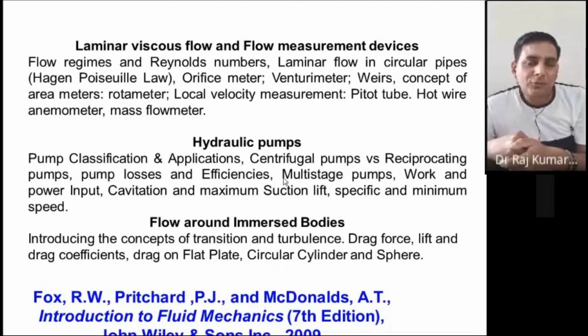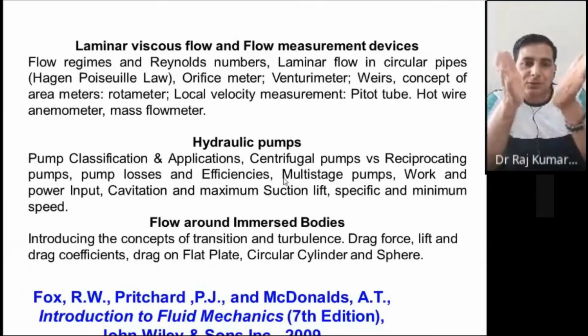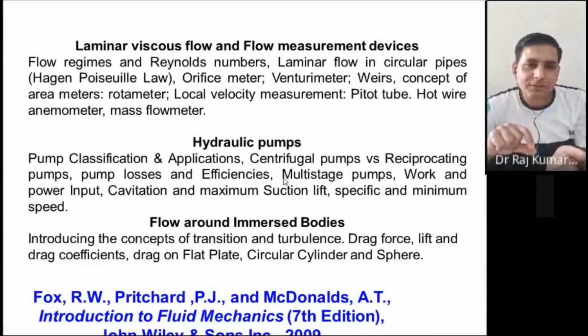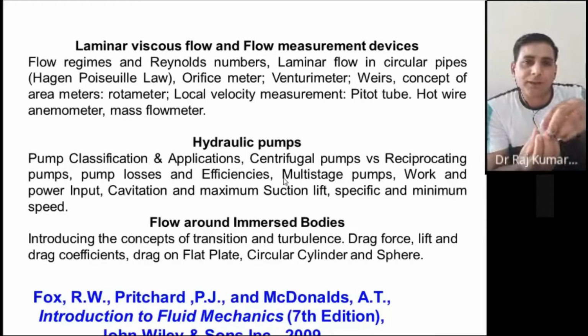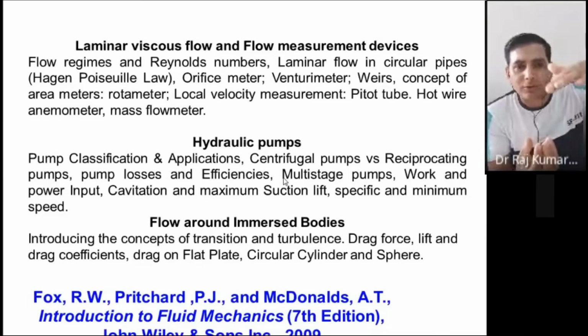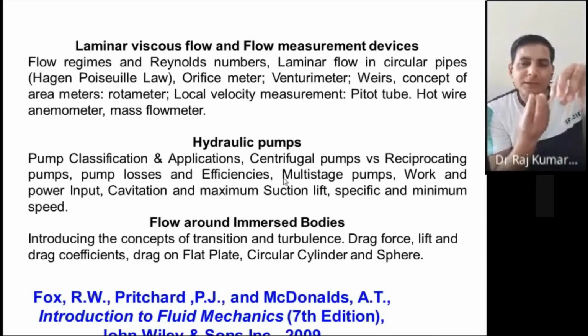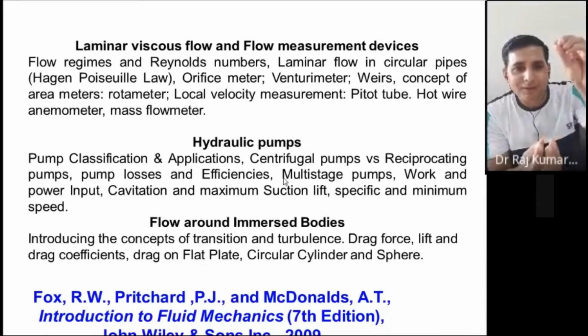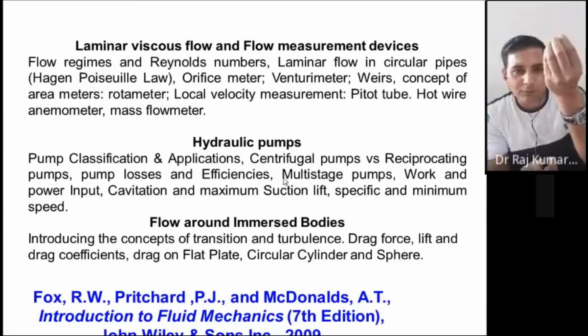Then you have the area meter, the rotameter actually. The rotameter is again a tapered cross section. On top it has a big cross section, and at the bottom it has a small one, and at the bottom you have a float. It works based on the concept of buoyancy. The more the force at the bottom, the more it will lift up, just like a ball. You might have seen kids with a plastic pipe like a bucket, and they put a ball in there. They just blow air, so the ball goes up, right? The rotameter also works on that concept. The more the force, the more the float will go up. Same thing as the ball concept.